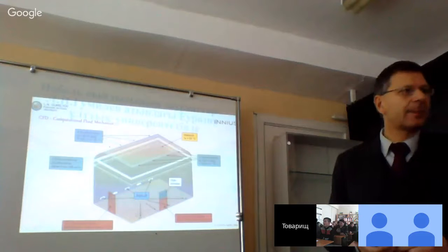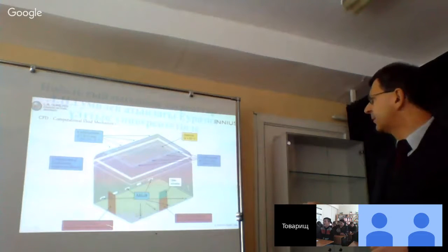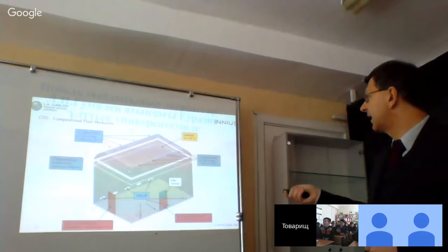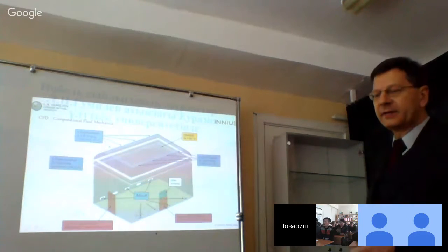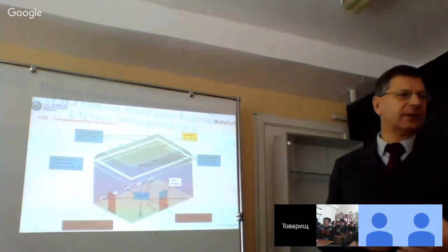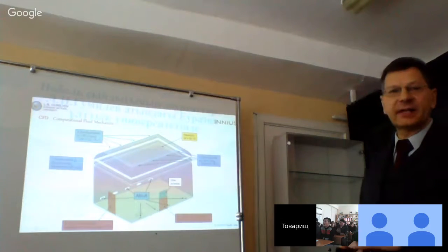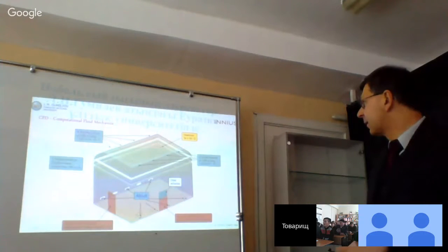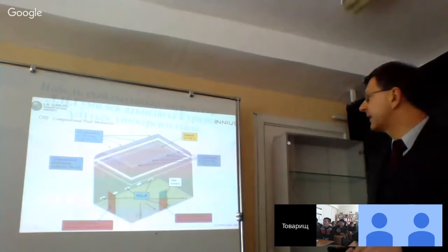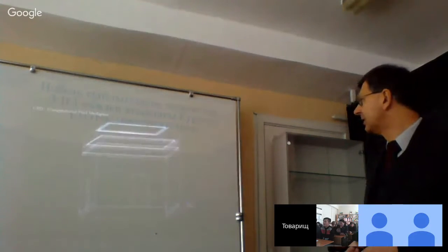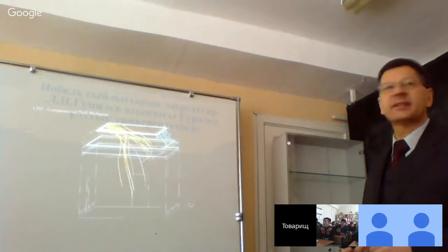In this example, we have an exhibition room where the supply air comes from the ceiling, wherever they decide to do this, but in this case it is so. And the exhaust air is near the ground. And now we research the airflow behavior in this room with CFD. And one result we have on the temperature and the air velocity and so on is that you can show how the air moves through the building, through the room, and that is shown in this video.